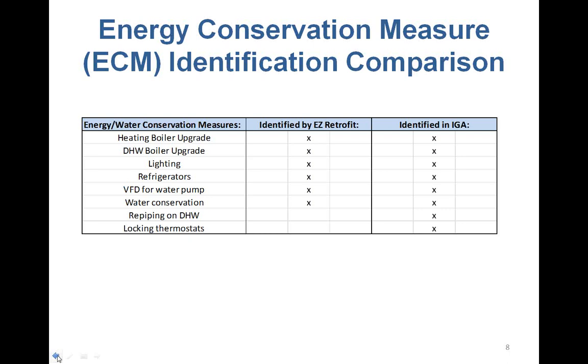And the locking thermostats, I think, were something that we've been looking at in a number of our buildings where we're looking at installing thermostats that have a preset at the factory limit. So they might only be able to go up to 74 or 76 degrees depending on the building. And I think that is something akin to what a lot of sites accomplish with programmable thermostats. This just offers the owner a little bit more control.